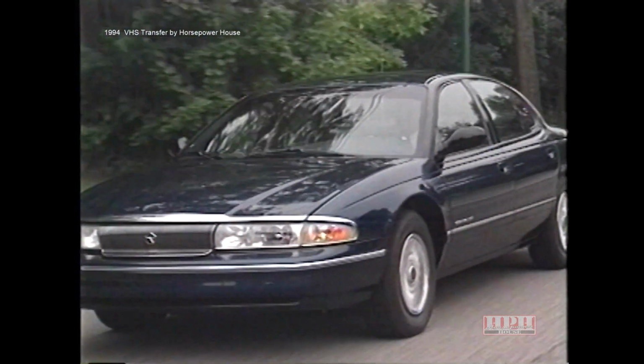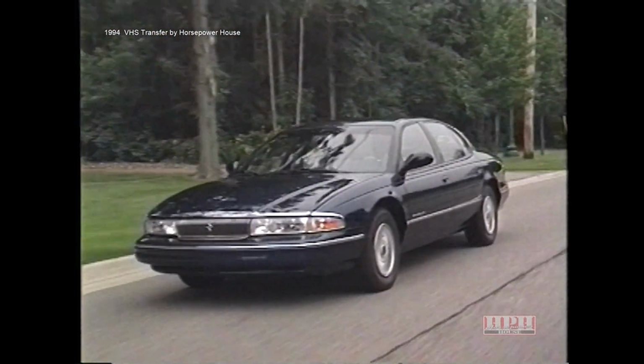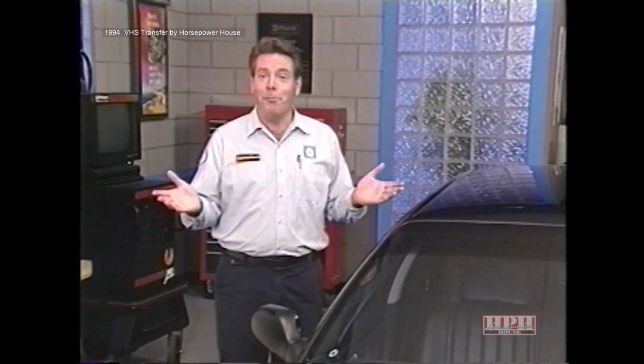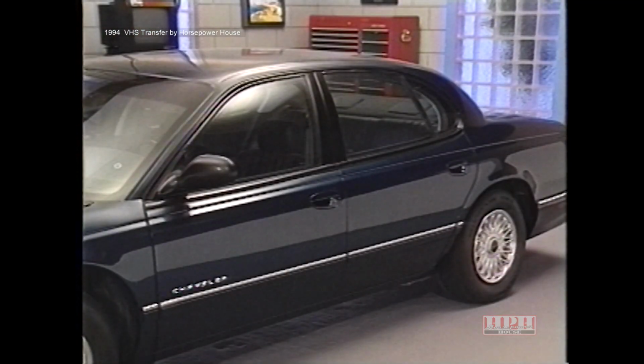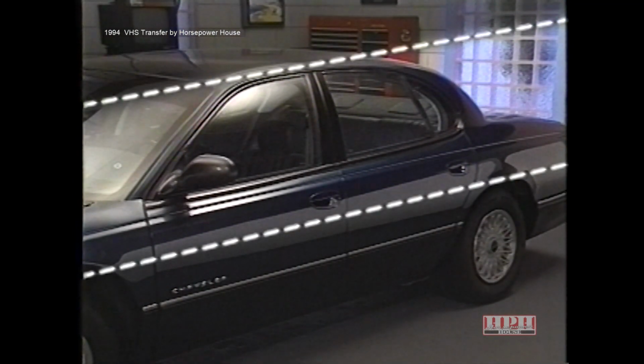A high-pitched whistle or sometimes a low rumble are the descriptions most often used when referring to external air seeping into the vehicle. Well, now we've covered the causes of air leaks and some of their symptoms. But where should you look for them? Air leaks are normally found in the upper side areas of the vehicle, down to about 1 foot below the belt line, because this is where inside and outside pressures differ the most.